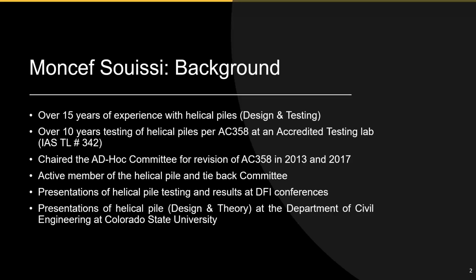My advisor contacted me and said, listen, you have all these test results from helical piles. Why don't you just change your subject and finish your PhD? So I went back in 2015 and I finished my PhD in 2019, and my thesis was about the capacity torque correlation, that torque correlation factor, KT. I'm going to talk a lot about it, and that's what my PhD was about. And I really think that the capacity torque correlation is probably the most significant attribute of helical piles. And you will see later on why.